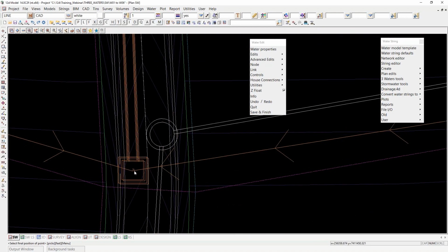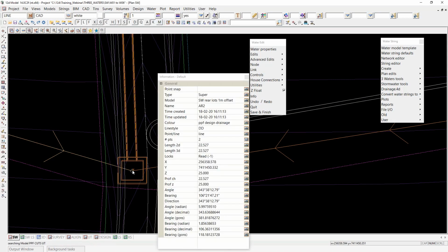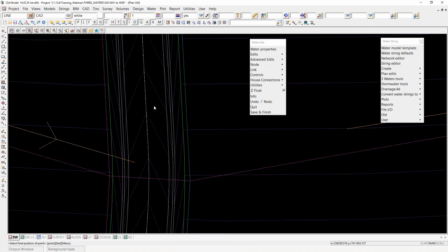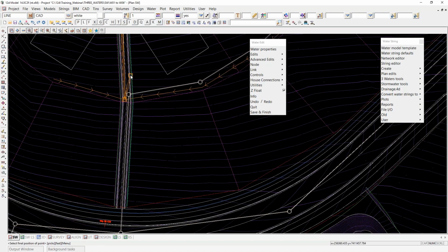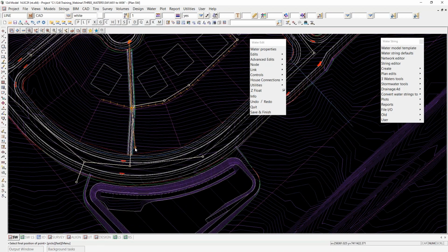But what I want to do for the second node here is create a manhole probably, but it'll still be a sag for now, but I'll change it to a manhole later, that's going to pick up the 2 incoming roof drainage lines here. So I'm going to make sure I snap right on the very end of one of these roof drainage lines in order to place my next node. Okay, so that's placed another. It looks like a sag pit still, or a rectangular pit. Ultimately, we'll change it a bit later on. So that's the second node in place.